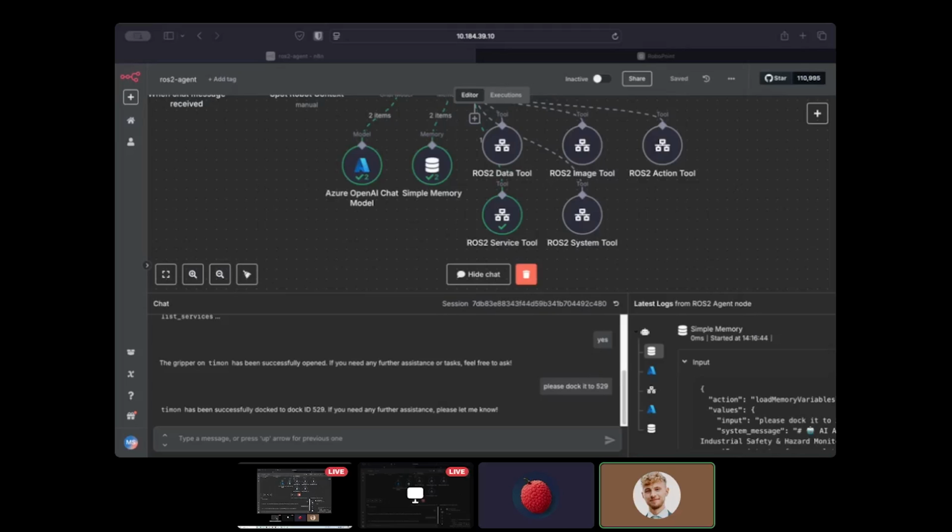And the second reason, in some use cases, you do not want to transport or to send any confidential data from the facilities where the robot is operating to any API in the cloud. So that's why I'm using a Jetson Orin AGX for my VLM. So everything is local. The robot doesn't have to send anything into the internet, and there is no internal data or images going to any internet API.